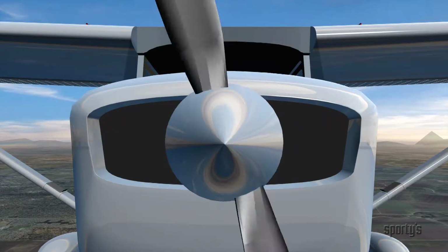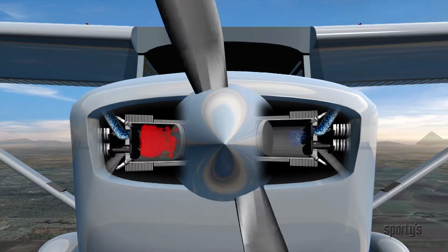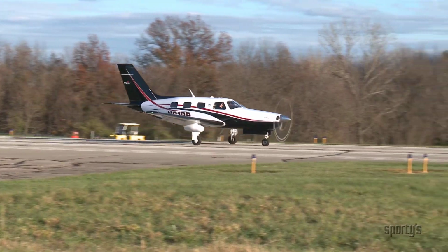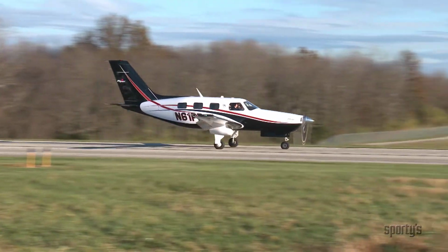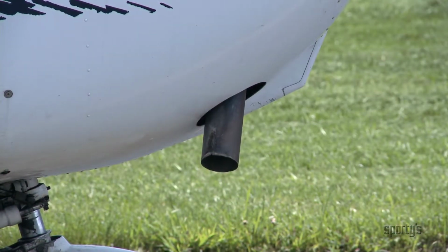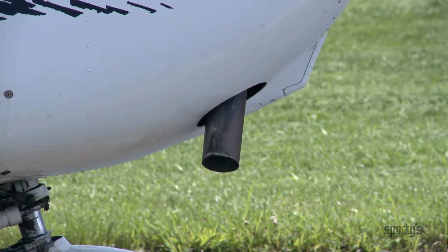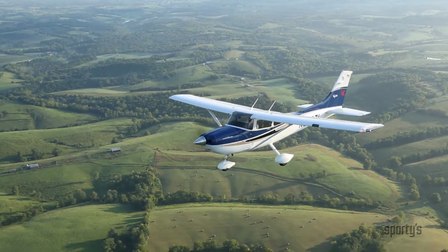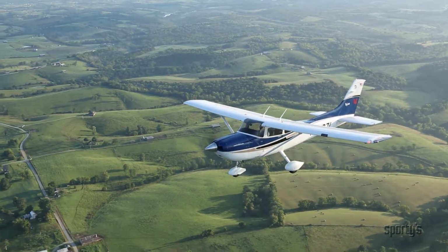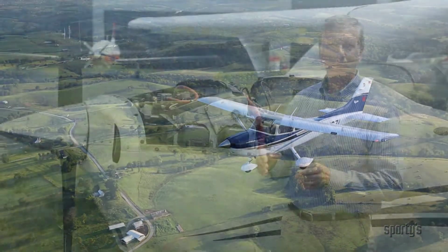No matter how many cylinders an engine has, each of the cylinders will complete the cycle every time the crankshaft makes 2 revolutions. More cylinders will make a smoother engine because there are more power strokes for each revolution of the crankshaft. Burning of the fuel-air mixture produces heat, and much of it is evacuated through the exhaust system. Remaining heat energy is dissipated through a combination of oil cooling and air directed over and around the engine.